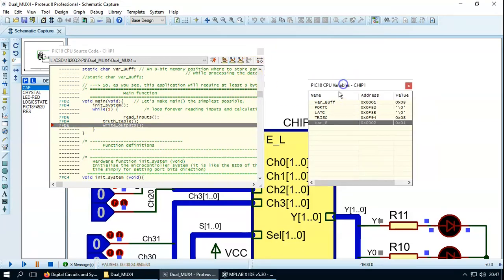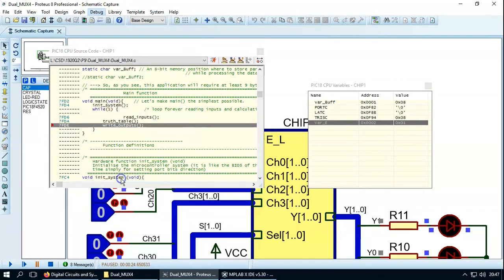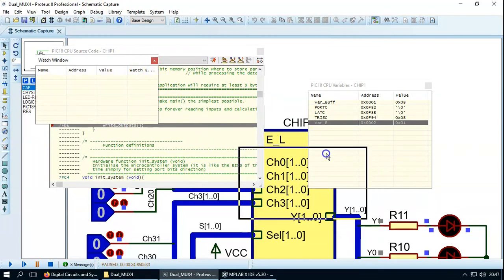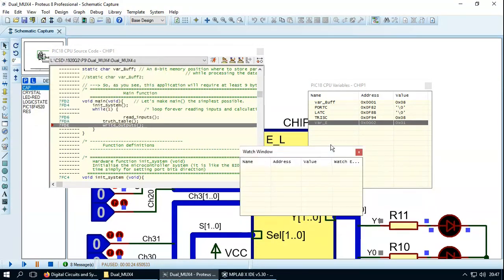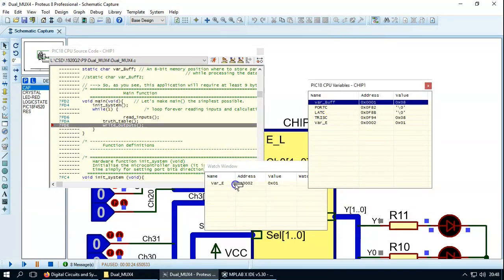And now, you see, if you go step by step, you have this list, but that is not that convenient, right? It is 1,000 times better to go to the book and get what is called a watch window. So that is what I like best here. And this is essentially why we pay for this software, right? This is what is valued. You see, you have something very interesting, which is this idea of dragging the variables from the variable window to the watch window. And here you can see the evolution of everything in time as long as you are executing instructions. You can see them all.